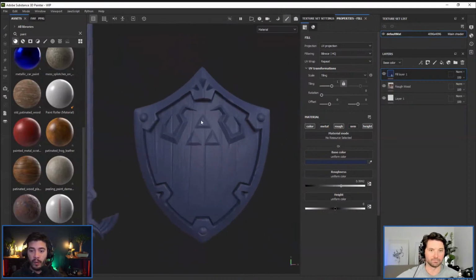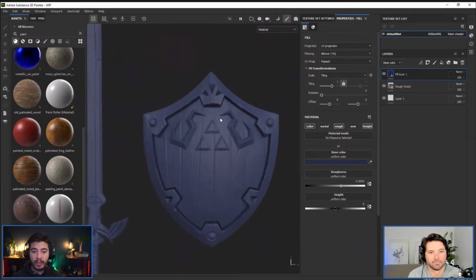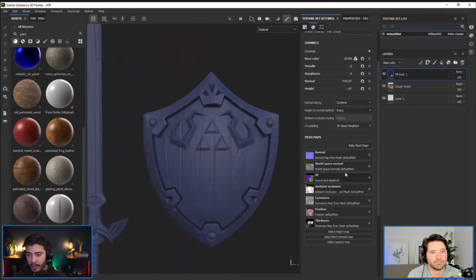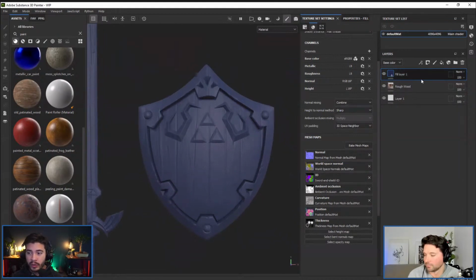All right. So what I'll show you now is that you can use one of the maps that I added. So the texture settings here, this one, the ID map, to isolate bits and pieces. So let's say that I want to only have the wood and the paint in its own masking group, right? Similar to Photoshop, you can just select both of these layers, Control G to group them together. Nothing happens right now. It's just a group that has everything. And I'm going to double click and call it wood and paint. All right. And literally we have just two layers, the wood and the paint.